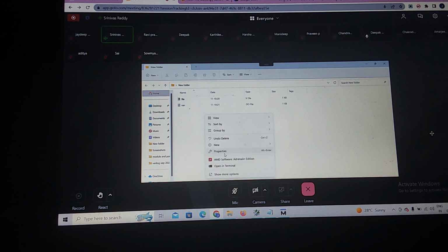One way to open ModelSim is right here. The usual way, as you know, is copying this address, opening ModelSim, then using the cd command to change the directory, putting the path in curly brackets. Then you execute the command called do. Do what file? The run.do file. You are doing the run.do file.